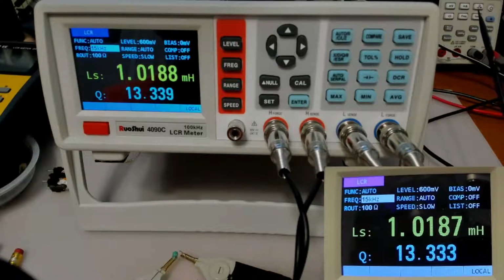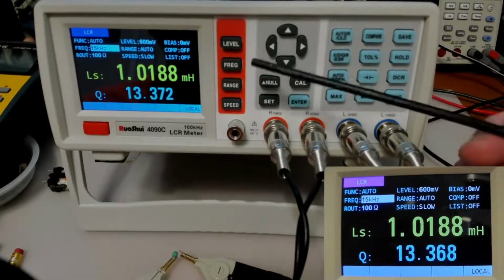As a rule of thumb, electrolytic capacitors should be tested at low frequency, and other components, especially small inductors, should be tested at a higher frequency, so their reactance is larger and the machine will be able to more accurately show the value. In any case, that's what that's all about.